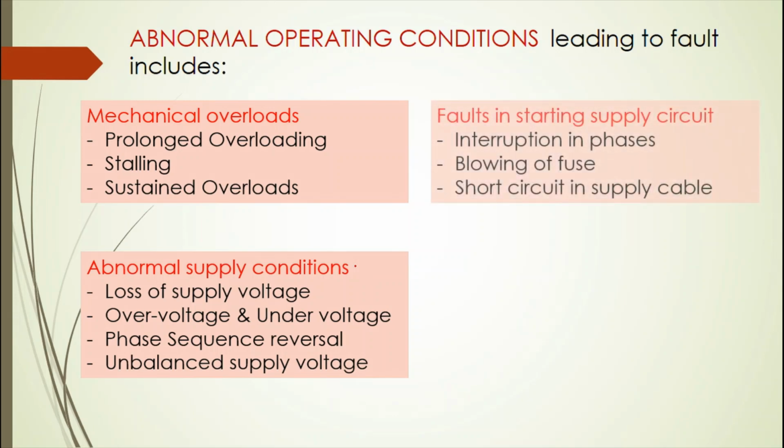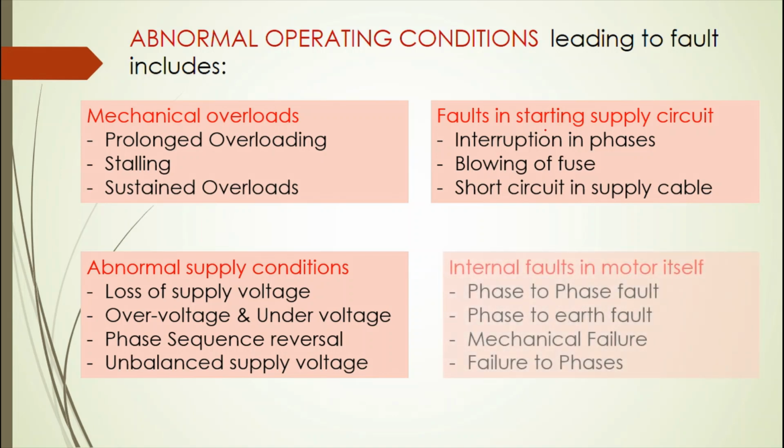Faults in starting supply circuit. If there is interruption in phases, or a fuse blows out, or a short circuit in the supply, it will definitely lead to a fault in the starting supply circuit. Internal faults like phase-to-phase fault, phase-to-earth fault, or mechanical failure or failure in one of the phases or all the phases will also lead to internal fault in the motor.